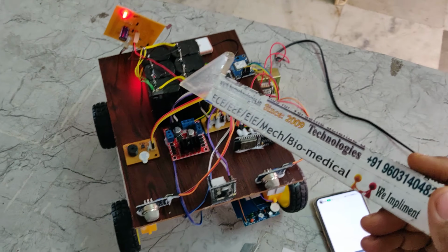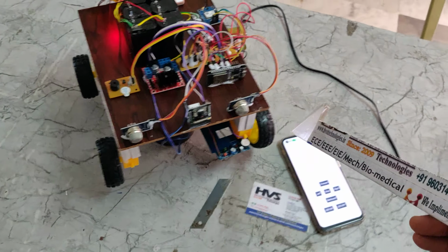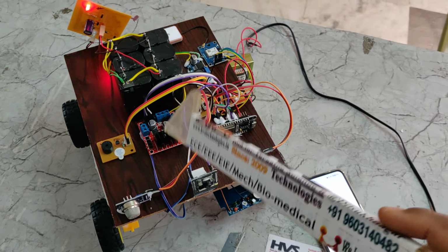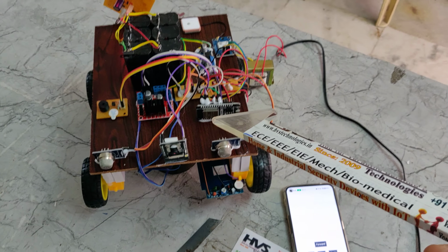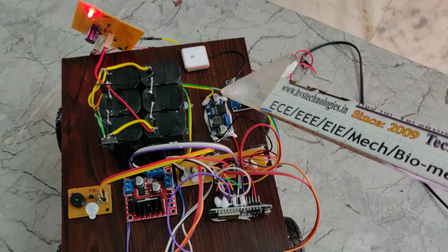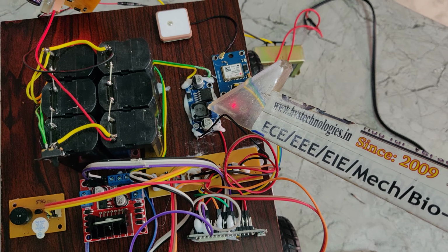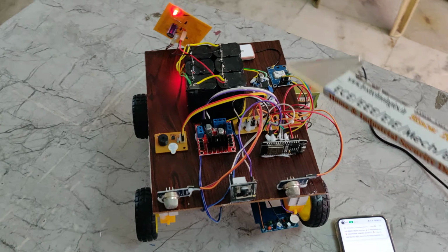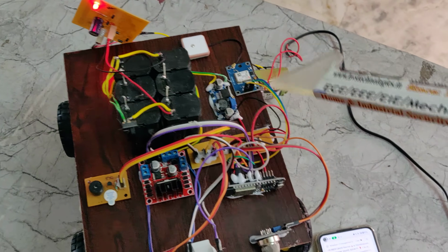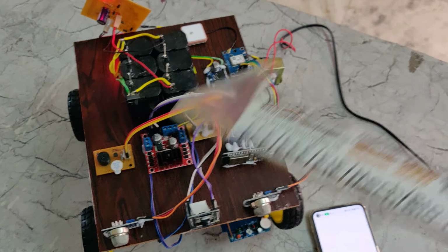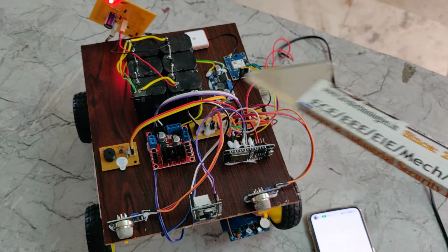That is the operating voltage of our motors, namely the robotic movements, and that is the input to the L298 motor driver. Coming to the remaining components, the operating voltage is 5 volts. In order to regulate that 5 volts from 12 volts, we are making use of this LM2596 voltage regulator, which takes 12 volts DC input and provides us 5 volts DC output, from there to this breadboard. From this breadboard, we distribute it throughout the input output modules of our project.